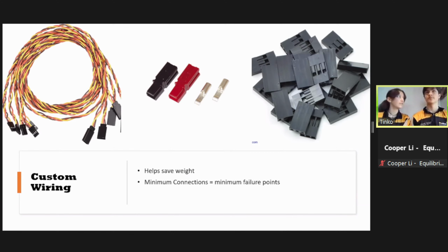You can buy them on REV. And like Kinzan was saying before, if you have the old Tamiya connections, you should probably switch them out to Powerpole, because the circular pins over time and over use will start to expand and they'll slip, so you'll have a lot of disconnections. If you are using the REV batteries, the JST, I think, you can fix the slipping using a knife and pronging the middle insert so it will expand outwards. Obviously, look at this before you do it, but those crimp connectors are also pretty good. Powerpole connectors are probably